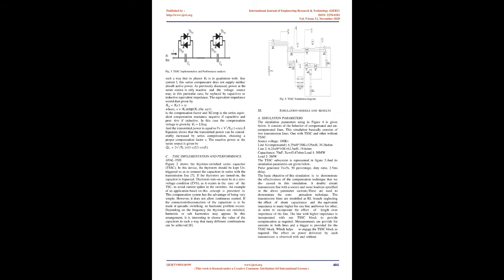In most of the applications the controllability is used to avoid cost-intensive or landscape-requiring extensions of power systems, for instance upgrades or additions of substations and power lines. FACTS devices provide a better adaptation to varying operational conditions and improve the usage of existing installations. The basic applications of FACTS devices are power flow control, increase of transmission capability, voltage control, reactive power compensation, stability improvement, power quality improvement, power conditioning, flicker mitigation, interconnection of renewable and distributed generation and storages.